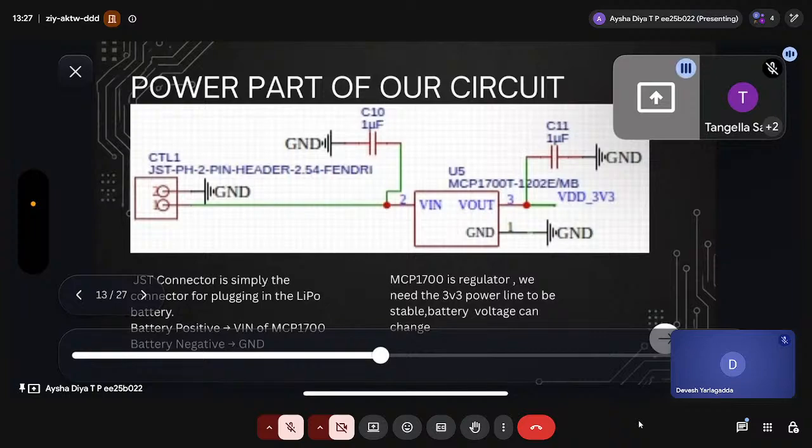Then we have the power part of our circuit. I already said we have a JST pin, which is actually a connector. We will be connecting our battery in this position. We will connect our battery's positive terminal to the VIN of our power regulator, and we need the negative part to act as the ground reference, right?